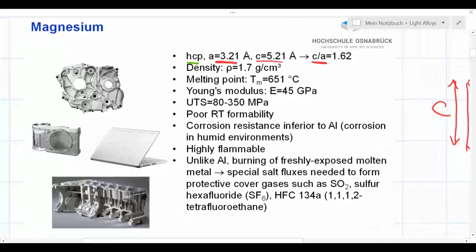We know that in general, HCP metals exhibit a poor ductility. For titanium, the ratio is even lower, but in terms of ductility, I would say that they are kind of comparable, right? If you have a titanium alloy with a good ductility, probably we expect 10, probably 20% of elongation, and the same also kind of applies to magnesium alloys. There are indeed a lot of factors which play a role. For example, grain size. If we could get HCP material with a fine grain size, we could expect a better formability, because with a single crystalline HCP, we must have a favorable orientation to activate glide systems.